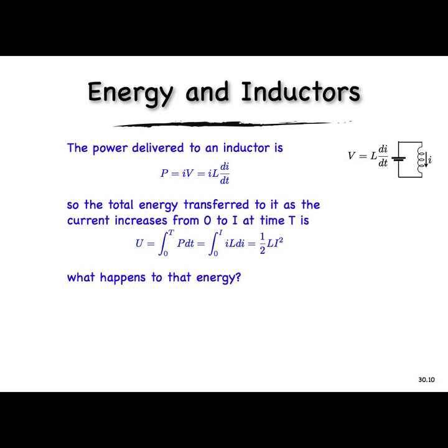Once you know that resistance, you can start putting current through and say the power it's going to dissipate is I squared R. So as it dissipates that much power, it's producing heat. That heat has to go somewhere. If you connect this to a heat sink or you put a fan on it, you can take that heat and carry it away and keep this cool. If you can do that, you can put more and more current through. If you don't do that, the heat goes into heating up and changing the temperature of this. And as it gets hot, you start to melt the insulation around these wires. And that produces that blue smoke that appears when you start playing around with these demos sometimes.